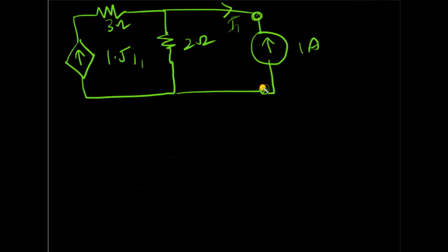So now I just need to find the voltage across these 2 points, and that would be my VOC. So let's see this through and solve the circuit. I'll apply mesh analysis, and I'll call this Ix to not confuse the numbers.